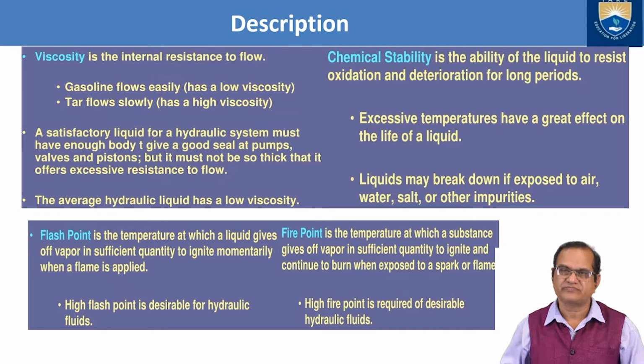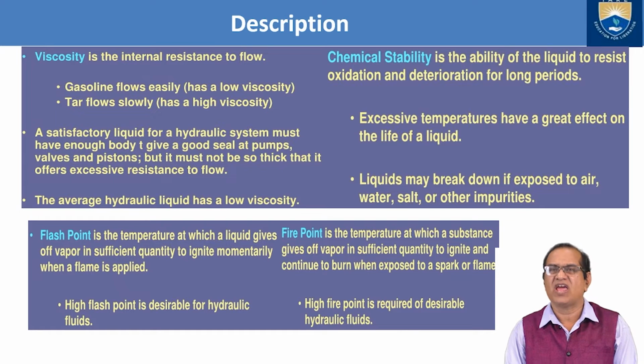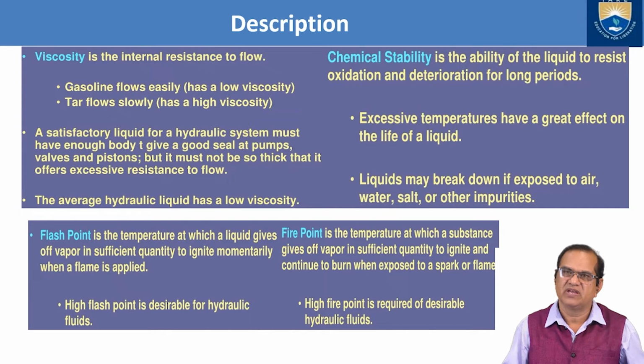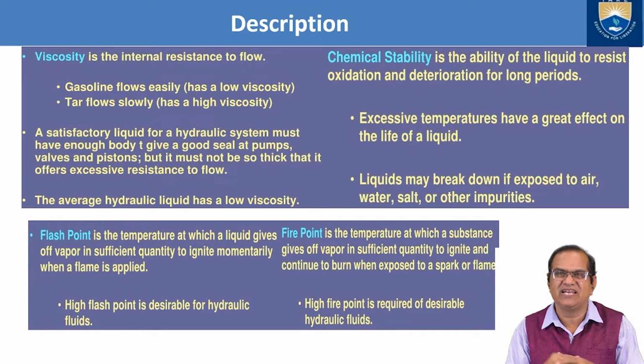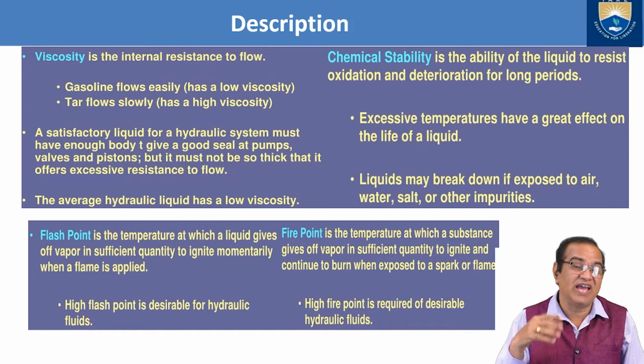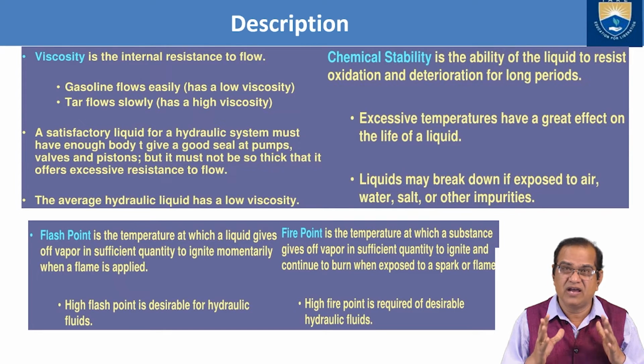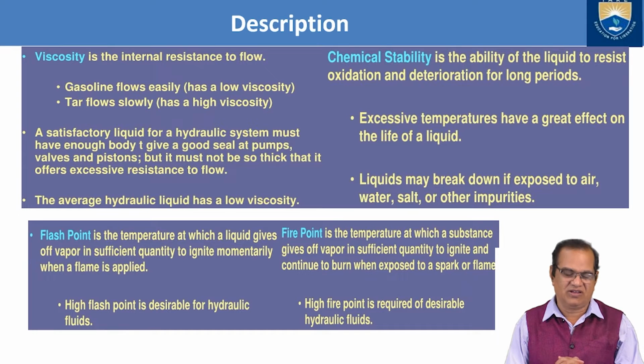be destroyed. Next is the flash point, the temperature at which a liquid gives off vapor in sufficient quantity to ignite momentarily when a flame is applied. A high flash point is desirable for hydraulic fluids. So the flash point should be high. Otherwise, at low temperature, if more vapors are generated, there are chances of fire. A momentary fire, for an instant of time, will take place, and if it propagates, it will start burning. So the flash point should be very high for hydraulic fluid.